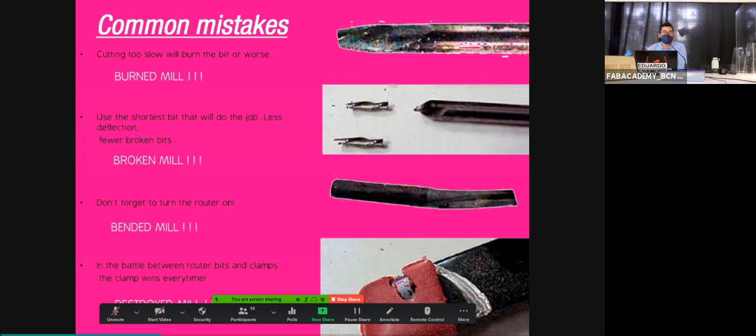One tip that we can do is we cut for 3 minutes, we stop the machine, and when the motor has stopped, we touch the end mill. You need to be able to touch the end mill with your fingers. If you cannot touch it because it's too hot or your fingers get burned, it means you are undercutting. It means you are cutting too slow. You will have heard that, but even so, you can always check by the temperature of the end mill. Exactly, there is not enough material, the chip, to cool down the end mill.